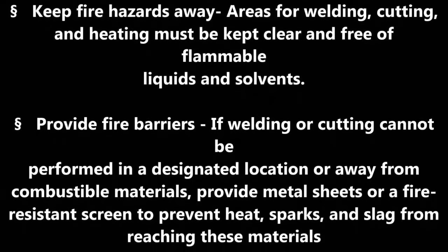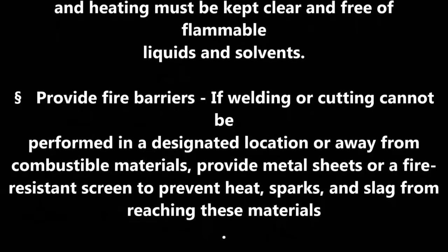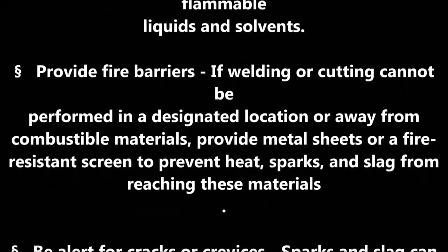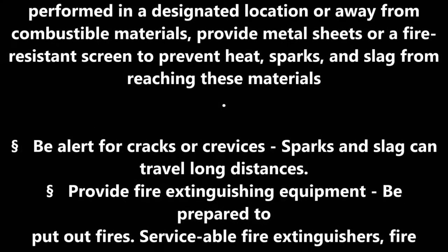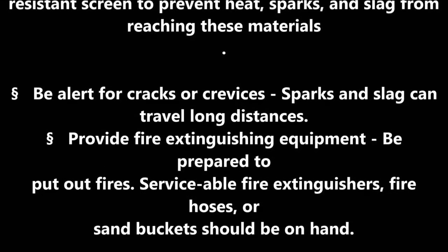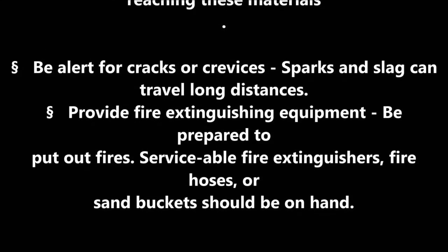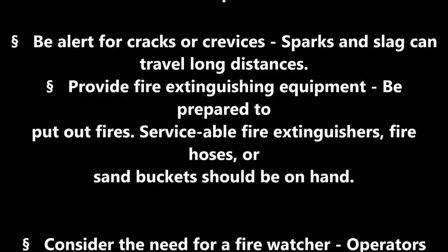solvents. Provide fire barriers. If welding or cutting cannot be performed in a designated location or away from combustible materials, provide metal sheets or a fire-resistant screen to prevent heat, sparks, and slag from reaching these materials. Be alert for cracks or crevices. Sparks and slag can travel long distances.